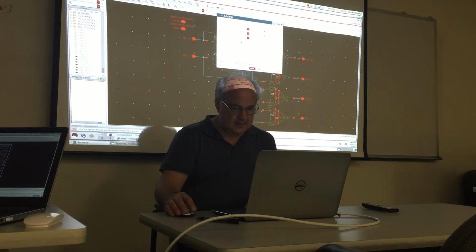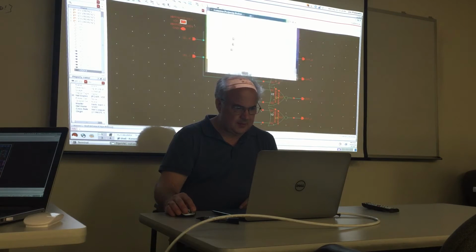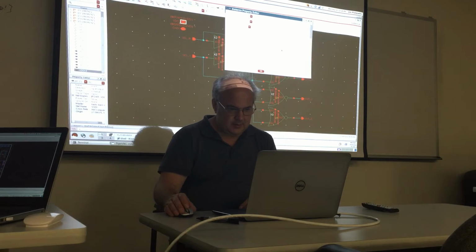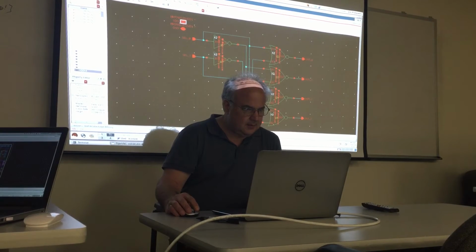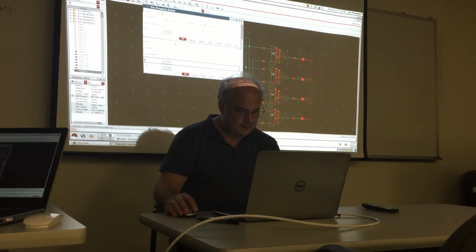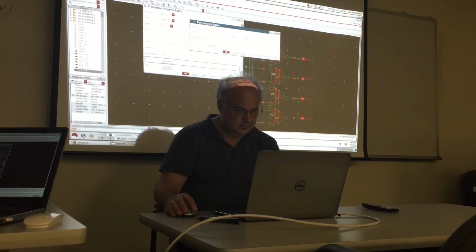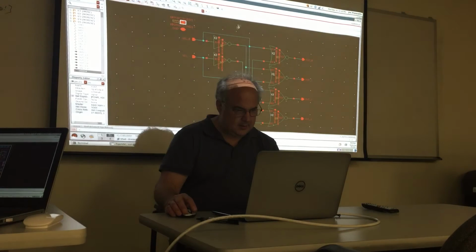I think if you click on an existing one and hit Q, you get those properties, and it shows you something weird. I don't know, I never understood why they give you certain things. It's not very consistent. You have to go into one of those expand menus from within the query. So hit Q, then scroll down and hit expand on pin and net, and it'll show you more detail about names and everything. Right. Interesting.